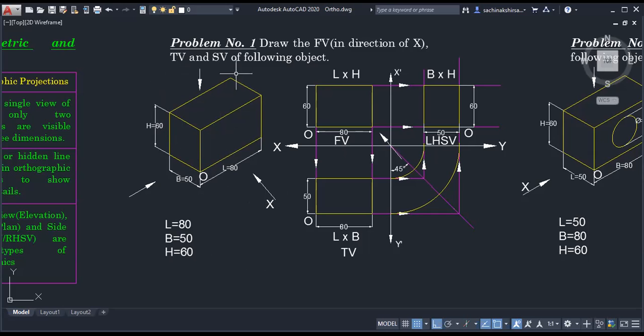In the previous lecture I also asked which dimension is the length. Somebody answered that the dimension which is greater is the length. Though that is correct in general, in our engineering graphics subject, I told you how to remember which is the length of the object. We have to consider the visualization direction. From that you have to see which is the horizontal dimension. That will be the length. It is not necessarily always greater than the width.